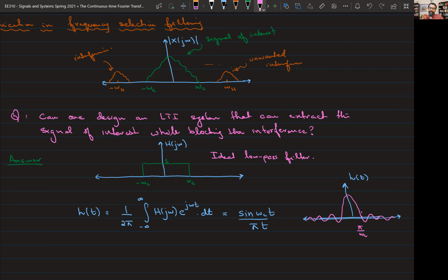So you could imagine a system which is not just this flat thing, but in different regimes it has different gains, and that's called equalization, right? So frequency domain analysis and this convolution property, it is because of that you come up with those designs. Okay.